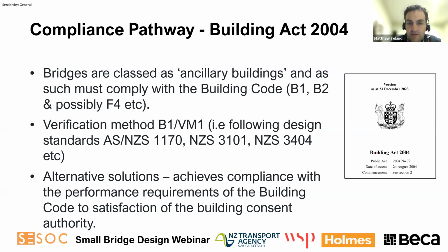There are the verification methods, so following the design standards like NZS 1170 and the material standards for concrete, NZS 3101, steel, 3404, and the timber standards. As Nigel mentioned before, another possible way is acceptable solutions, but there aren't really any that are suitable for bridge structures. That leaves us with the third option, which is alternative solutions. The key with an alternative solution is that it needs to achieve compliance with the performance requirements of the building code to the satisfaction of the consent authority.